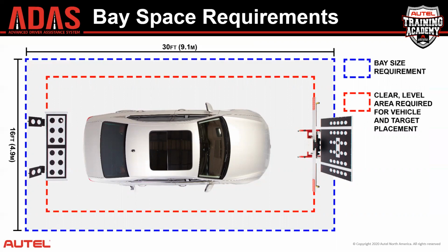However, the OEMs require that these service bays are flat and level. And that's really an important feature for accurate calibrations. However, most service bays and repair shops were specifically designed not to be flat and level, to allow water to drain. Well, you have to take that into account as you get into your new calibration business, or you start to offer calibration service in your existing business. A flat and level bay is really important to accurate calibrations.